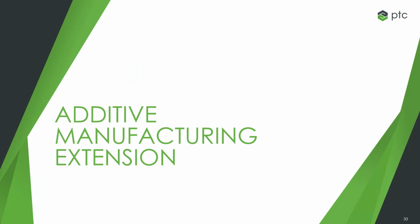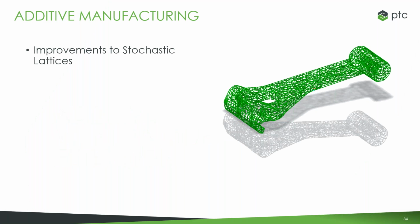So a big advancement there, but also enhancements around some of the things that we've been building out over the past couple of releases of Creo, such as in the world of additive manufacturing and 3D printing. And the first thing here is with the creation of stochastic lattices. We've enhanced the way that the lattice type follows along some of these hard edges on the outside of our parts, so it makes those structures even more structurally sound.